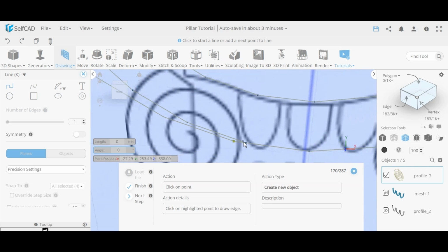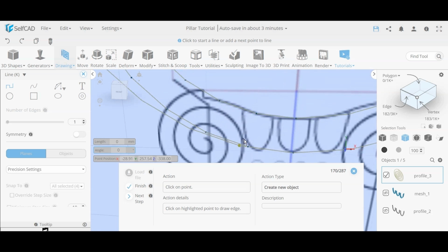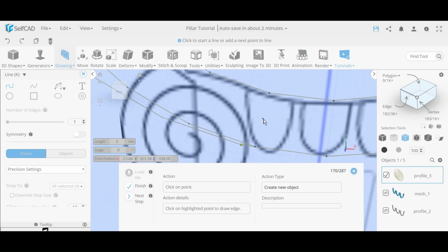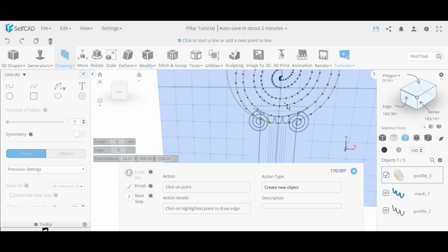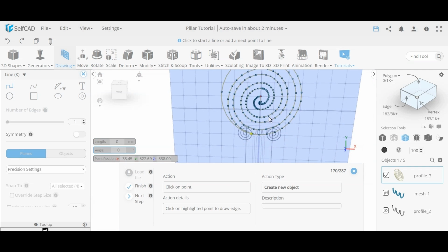And later we're going to start extruding this, making them as a separate part, which will end up being a mesh that actually collapses at a single edge, which makes it actually non-manifold in some cases. In the case like this, you see later the design, this actually makes it non-manifold. So our goal here is to make it the same thing we have over here, that it ends at a line. But we're going to make it a tiny line, but we want them to finish at a line, not at a single edge, which will later make some issues.